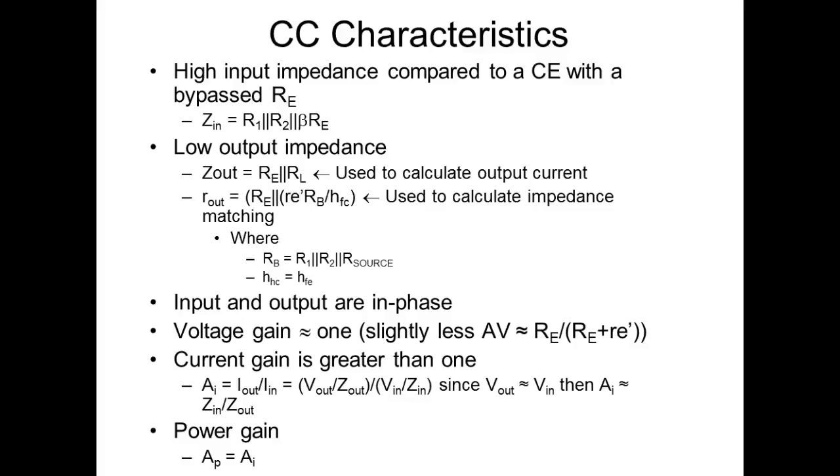So it has a high input impedance and a low output impedance, so that's what we do. So we use a common collector to drive low impedance loads or low resistance loads. So this is the output on the power supply. Because when we start loading a power supply, we're dealing with low resistance loads, right? You understand? So we use common collectors to drive power supplies.